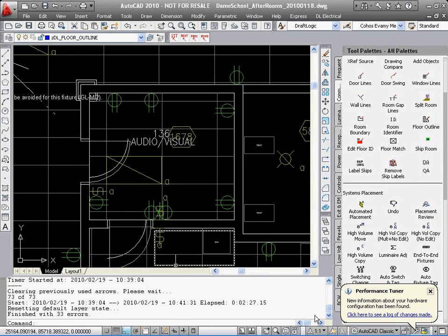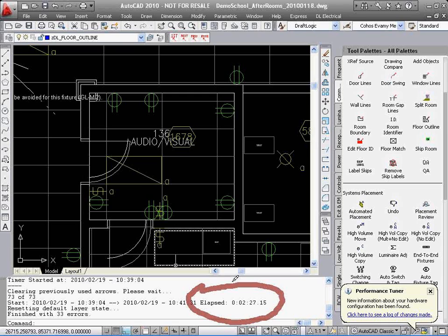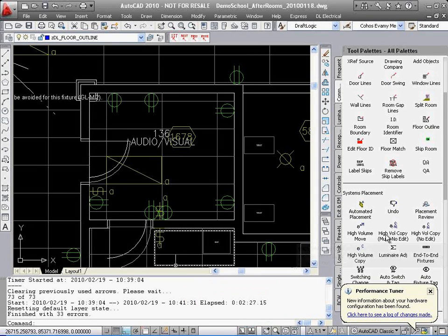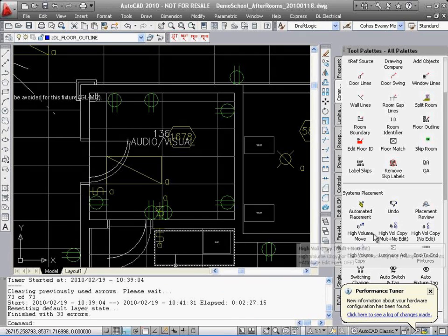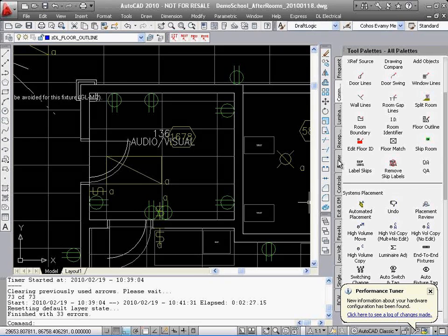Once the designer is happy with all the layouts, we move on to auto circuiting, which is where the real power of the program is clearly evident. The application will circuit this project in about 30 seconds. That provides the data to complete all the schedules, as the software now knows where all the lights, plugs, motors, and other devices are, and can populate all the schedules with that information.